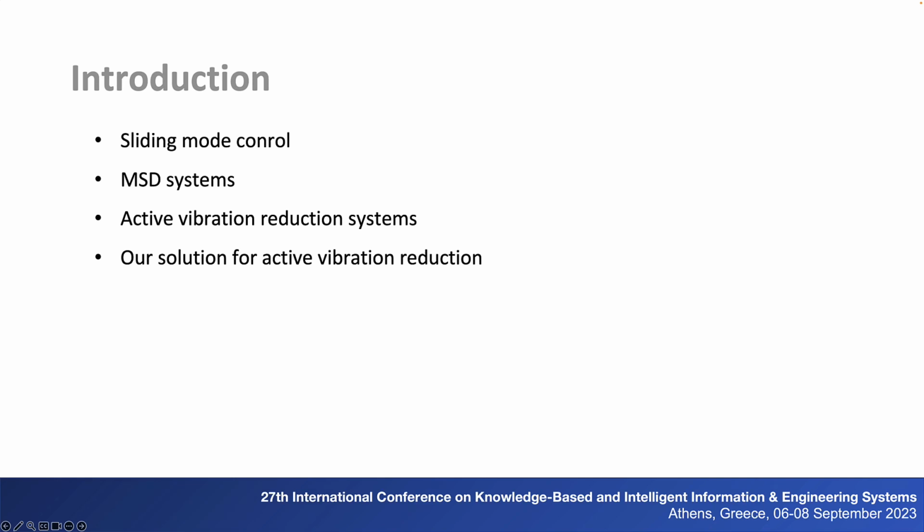There are a lot of methods to implement the SMC controller. In general, the design procedure is based on two phases: the reaching phase where the system drives to a stable manifold in a finite time, and the sliding phase where the system slides to an equilibrium point.